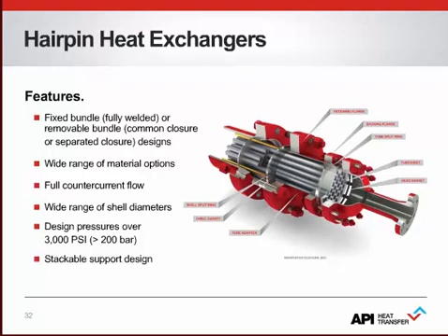Design pressures typical of a TEMA shell and tube are common, again lending flexibility as an alternate to the more traditional shell and tube heat exchanger. And lastly, standard support and channel designs are stackable, making multiple hairpin units piped up in series or parallel a very easy design option.